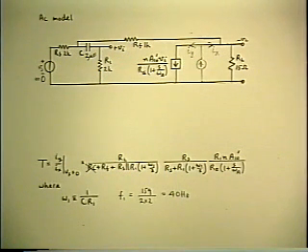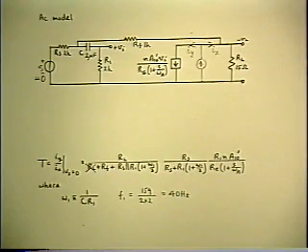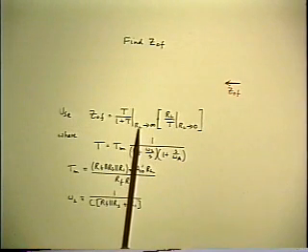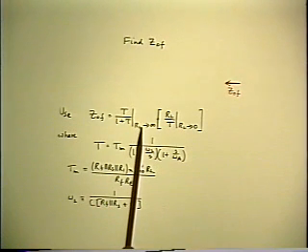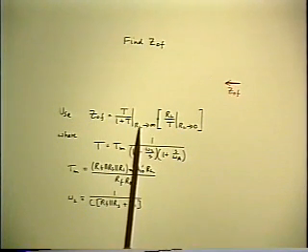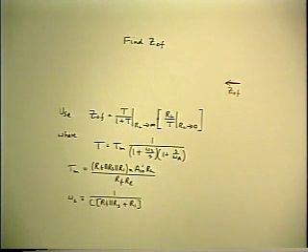But something else happened to invalidate that approximation. You see what that was? How did we evaluate the output impedance? We used a formula that required us to let RL go to infinity. If we've already dropped RL compared to something else added to it, we're not allowed to let it go to infinity. That invalidates the approximation.